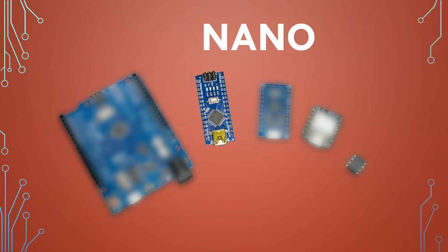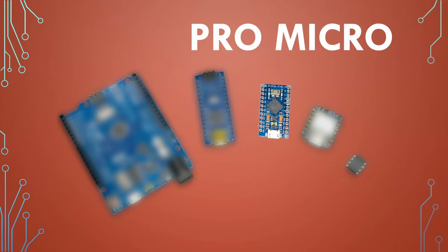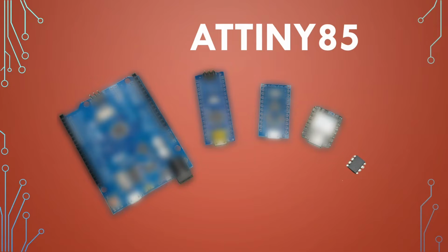I use this board quite a lot when I need something small. This board only has solder connections, but you can get them with pre-soldered pins and use them in breakout boards like this one. Getting even smaller, we have the Arduino Pro Micro. And smaller still, the Arduino Xiao board, which is quickly becoming one of my favorites. Don't let the size fool you, as this board has a processor 4 times as fast as the Uno. This board also has built-in Bluetooth Low Energy, or BLE, so you can control it with a cell phone. Last is the ATtiny85 chip that, as you can see, is in fact very tiny.